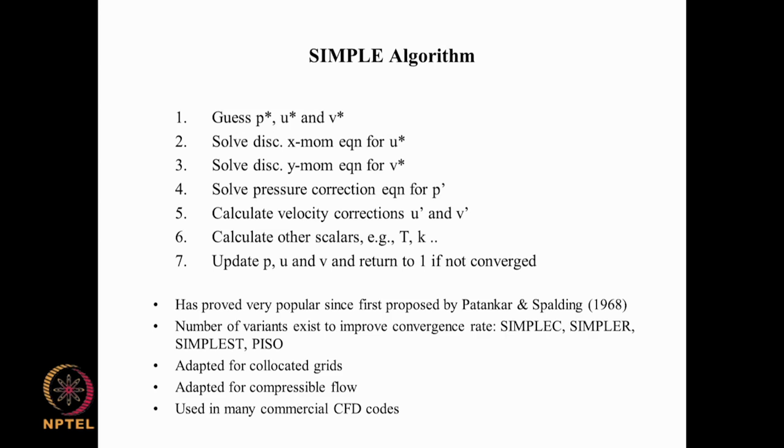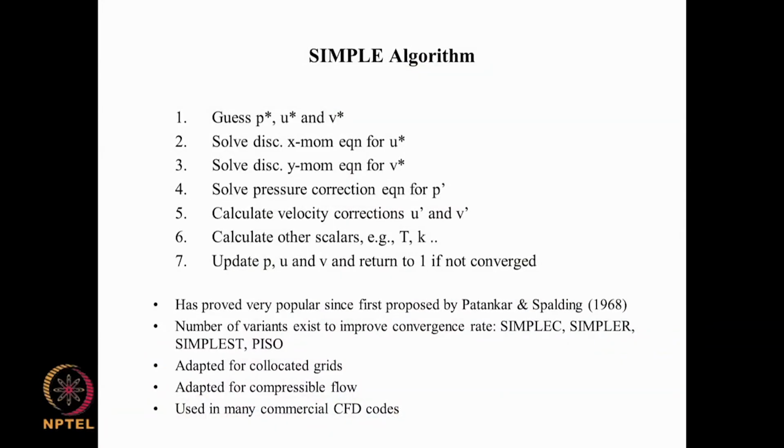They increase the number of equations. So when you have so many coupled equations, we have to make incremental variations, and this method allows those kind of incremental variations to be brought in properly, and that is also one of the reasons why this has become very popular for incompressible flow calculations, where usually a lot more physics of the problem is tackled than in compressible flows. So the SIMPLE method, in terms of its variants and latest variants, is the one that is invariably used for many computations of incompressible or nearly incompressible flows.